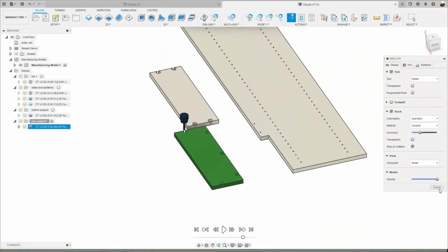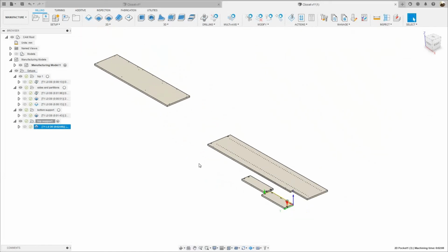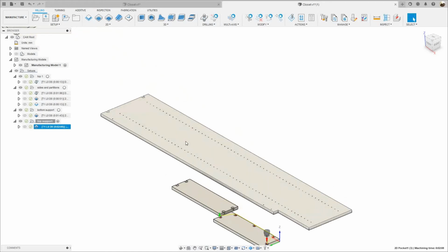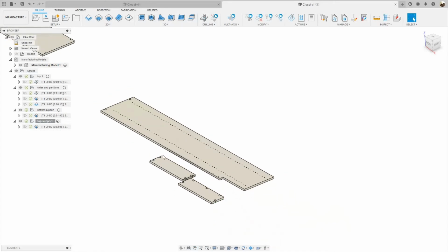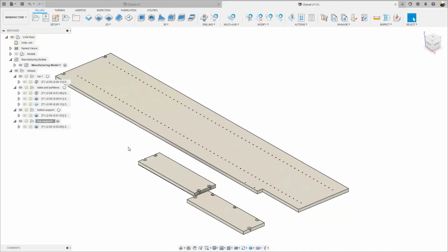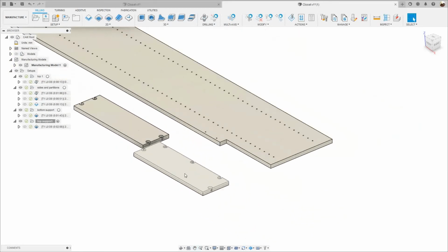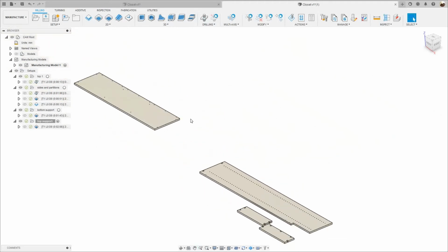There you have it. So I programmed just 4 parts. This one program is gonna create 4 parts depending on how you mirror the program on the machine, so you have to be careful with that. These guys right here, I don't have to mirror this guy, so it's gonna be one program for 3 parts for this guy, and one program for 3 parts for this top support panel, and it's just gonna be one program for that top panel.